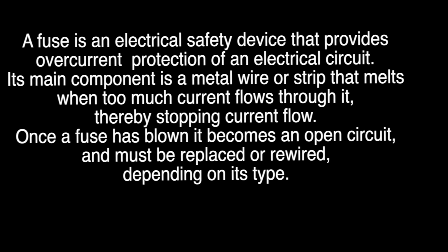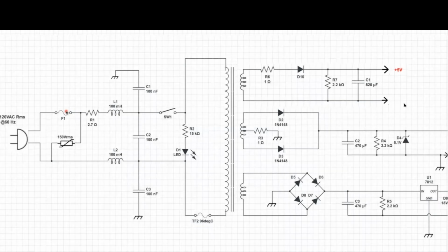Now, sometimes you'll see a fuse that just has a little break in the wire. And other times you'll see the whole fuse turn black and silver and has all this melted metal in it. It all depends on how much current flowed through it. Maybe there was a short circuit or a big power surge, and that fuse blew violently. On the other hand, sometimes fuses just fatigue over time, and they get a little break in them, and you can just pop that fuse in, and the thing works again.